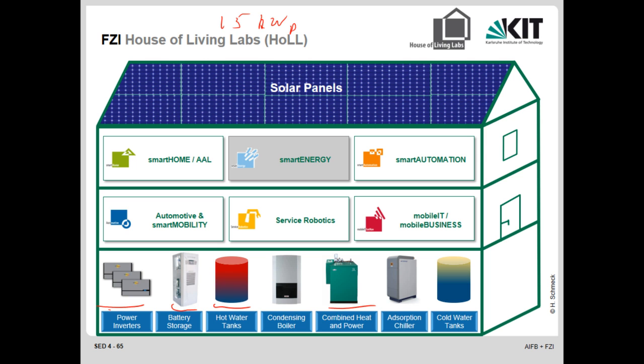But when there is more need or heavy need for heat, we need a condensing boiler, another device for providing heat. And so we have the hot water tank for that. And then we would also like to use our combined heat and power plant in the summer, but there you don't need heat, but you need cold water if you want to have air conditioning.